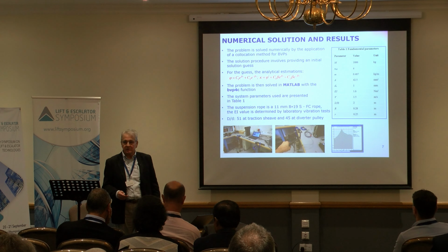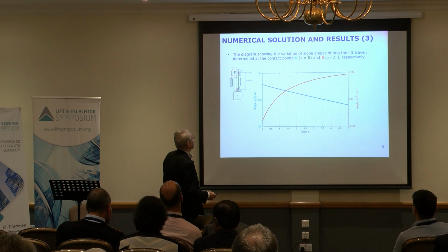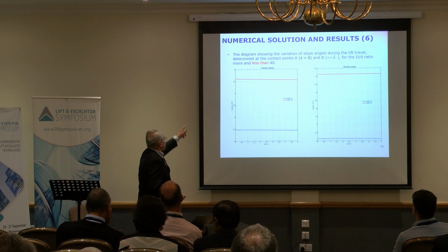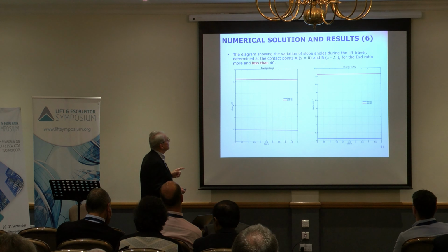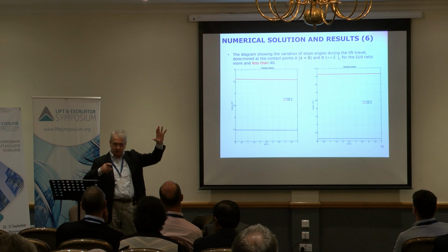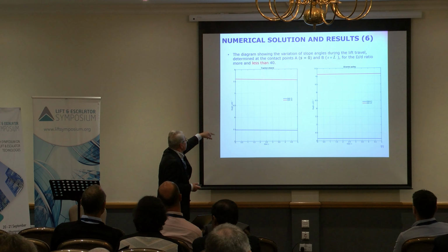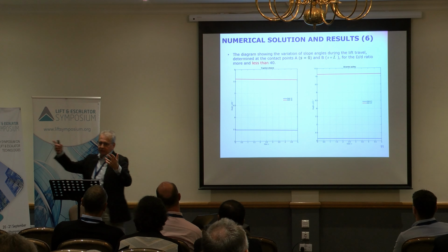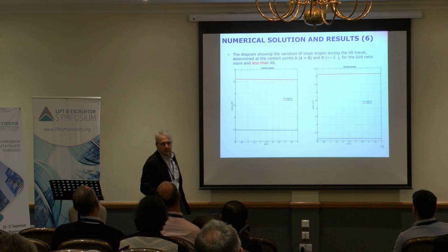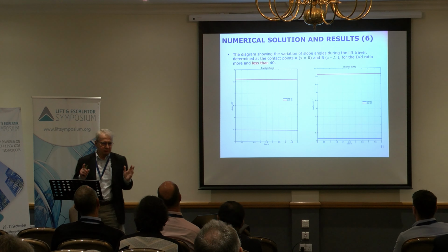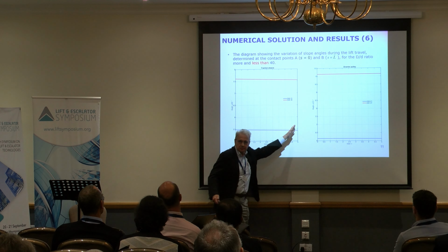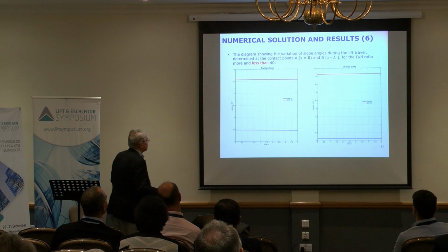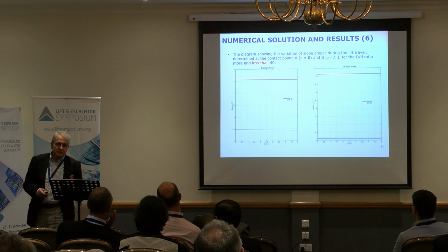Now, what happens if we change it? So the change now, I go back, again, the same simulation, and that's what we get. So that's diagram showing slope during the travel. So that's the angle at the top, remember that. The blue line is for over 40. The red line is less than 40. It is approximately sort of 36 or so. And you see that there's a difference, quite substantial. So that's a traction sheave and diverted pulley, both, okay? So the same we'll see when we now calculate bending stress, okay?